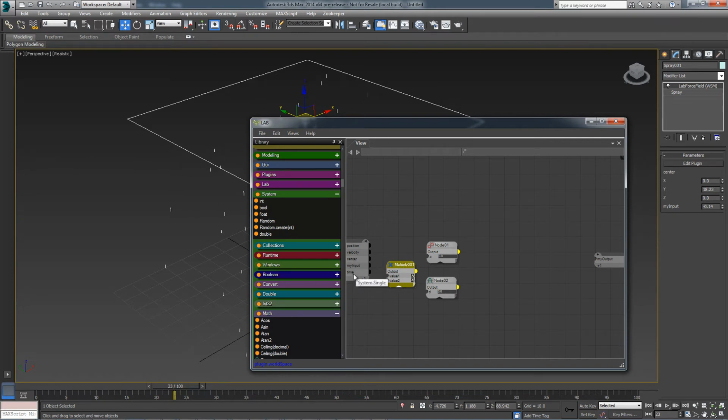So I'll wire it here, and as the second value I'll just create another input into our plugin. So we have our input here, and I'll just set it to a small value like 1 for now. So this scene time multiplied by this value, I will now wire into the inputs for sine and cosine.